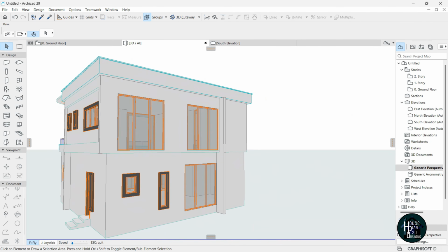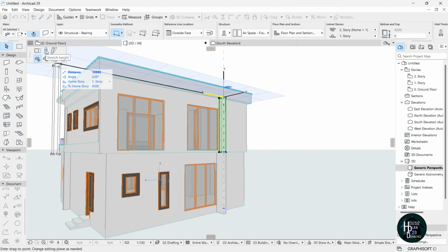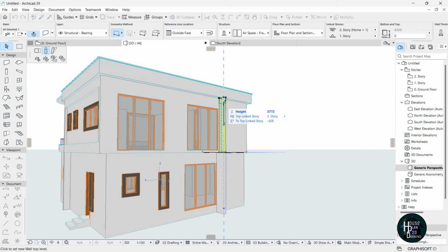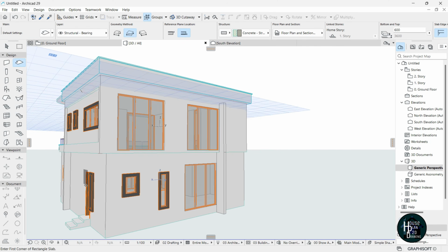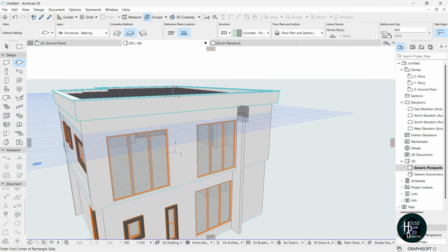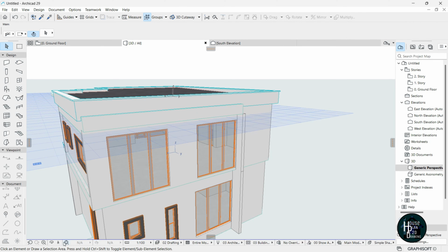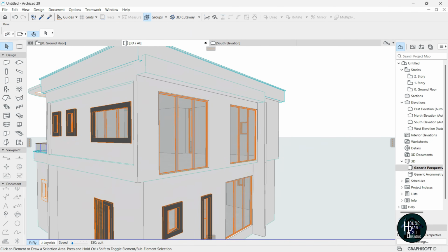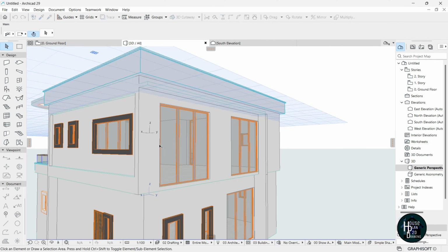So for this other side, what you want to do is just click this, click on this node, click on the stretch height and reduce the height to something around here. Okay, now I'm going to hold down Alt and select this. Okay, I'm just going to click that edge there and move it to this side here. Okay, now what I want to do next is just adjust this properly. So I'm just going to click on this and reduce it to something like this.